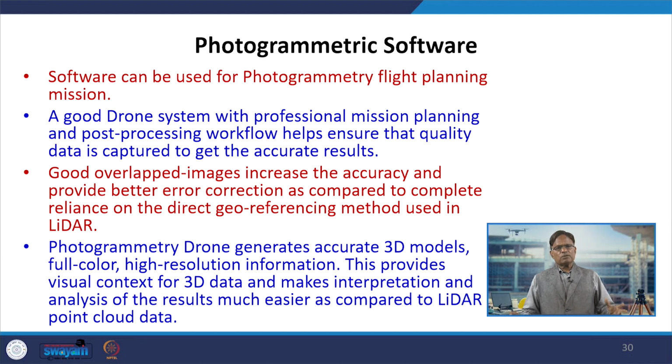Photogrammetric drones will generate very accurate 3D maps, fully color, high resolution information, and this provides us visual context for 3D data and makes the interpretation and analysis much easier as compared to the LiDAR point cloud data, because photographically we can see the details also in that model.